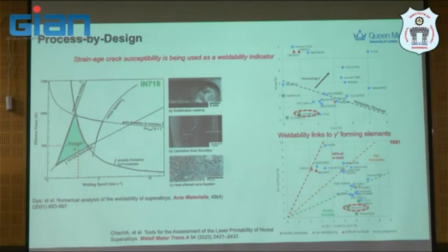study, I think back in actually 1940 or something like that, there's a paper in the US that tried to identify, okay, this material is actually not printable, not weldable at that time, and then this one is printable, indicated by the green color here. This is actually weldable or printable material for existing nickel-based superalloy. So when gamma prime is increasing here, they believe that, but I'm quite interested in this diagram because there's no gamma prime during 3D printing,